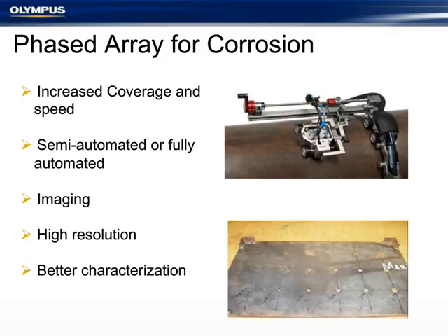Moves very rapidly, but it's just one sensor, and we really rely on the fast-moving mechanic in order to be productive. So phased array was a very good candidate to improve this process. With phased array, as you can see here, we can put this on a manual scanner, cover like a 12-inch grid. We actually encode in both axes, so we're basically painting a complete image of the area that we're going over. Or we can actually put it in a fully automatic scanner.